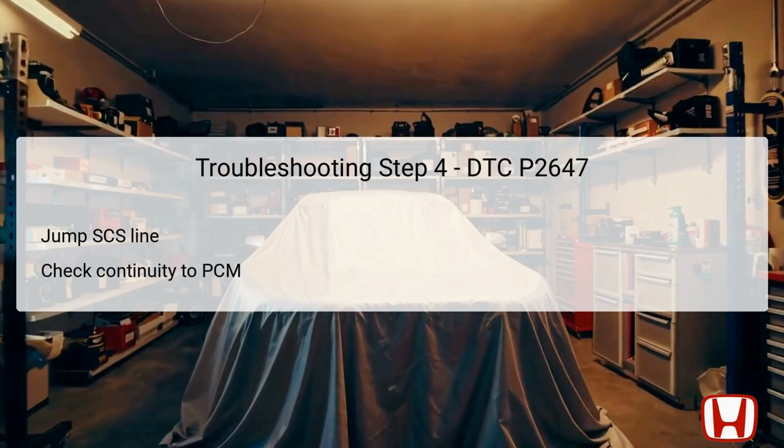If continuity is confirmed, the wiring is intact, and the technician can move forward to the next troubleshooting step. However, if continuity fails, an open circuit in the VTM wire must be repaired, ensuring that the signal reaches the appropriate components within the system.